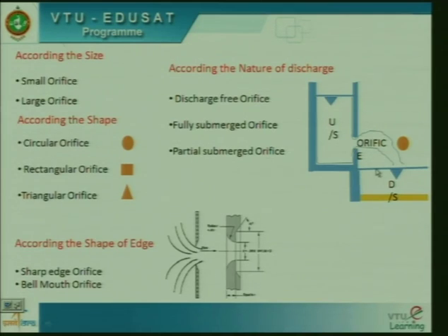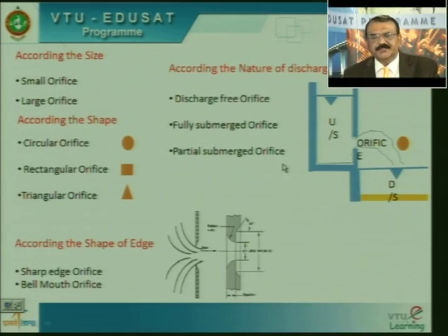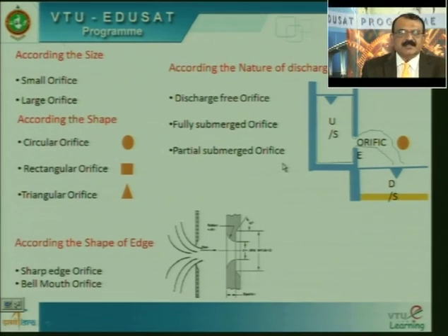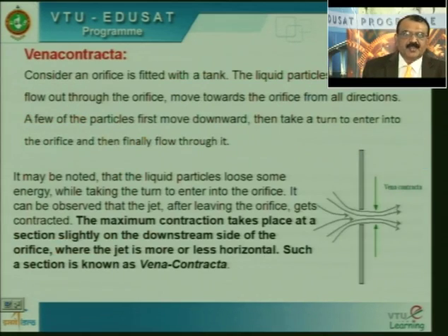This is discharging free, this is completely submerged. If the level of water is between this top edge and the bottom edge, then this behaves as a partially submerged orifice. This is the classification of different types of orifices. I hope it is clear.